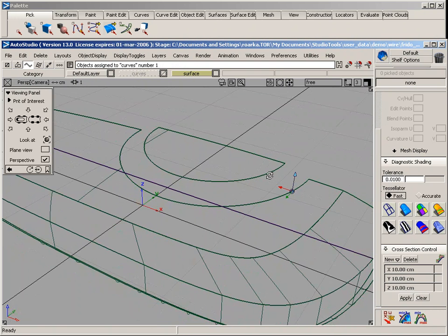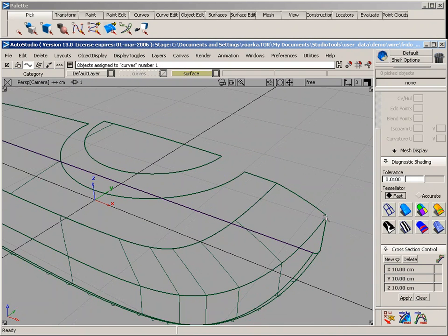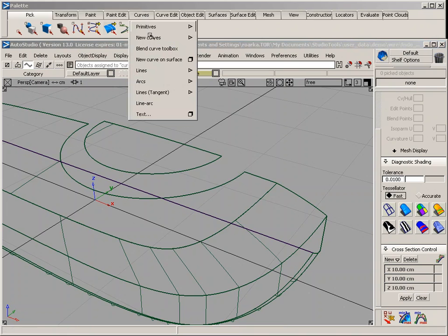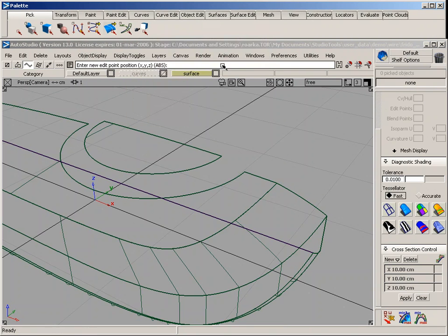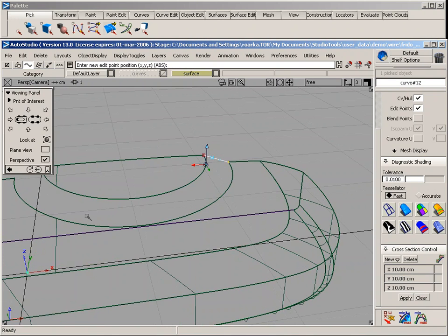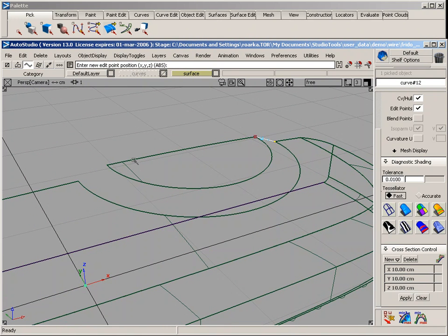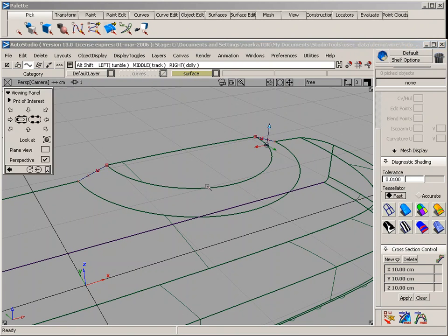Now for this, previously when I placed the curve over here, I just used the CVs to place it in the side view. In this case, I'm going to use a curve with edit points. This is going to allow me to hold down Alt Control, snap the first edit point on that edge and the next one over here. So this is a fast way of just creating a perfectly straight curve in between 2 points. I'm going to repeat the process over here. Go to Pick Nothing and place the next 2 edit points onto the edges of the 2 trims.